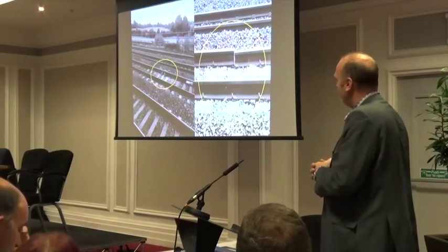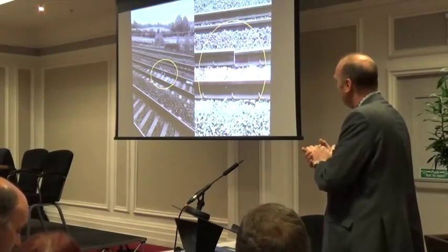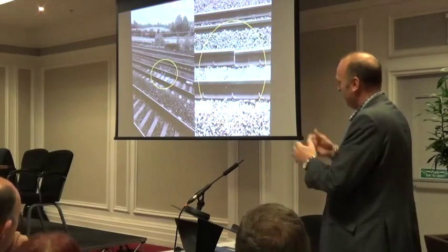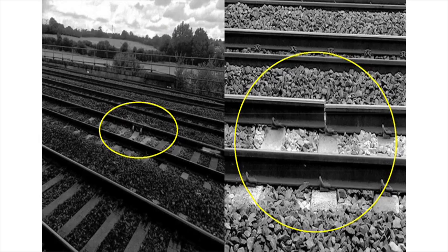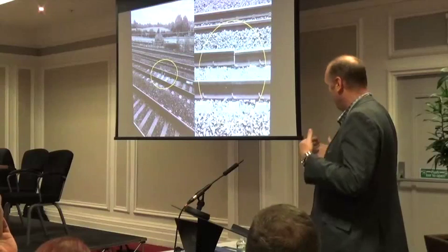That's not something you want to run any traffic over, or certainly not for any length of time. Although it's nominally supported, it's on a sleeper. You can see there how the sleeper's dropped and there's a difference in movement there. But a lot of that's the dynamic movement of the track underneath it. Again, the whitening of the ballast. In the picture on the left, we've got a temporary clamp on it to run it at low speed. But again, look in the background, there's your structure, right on the transition.